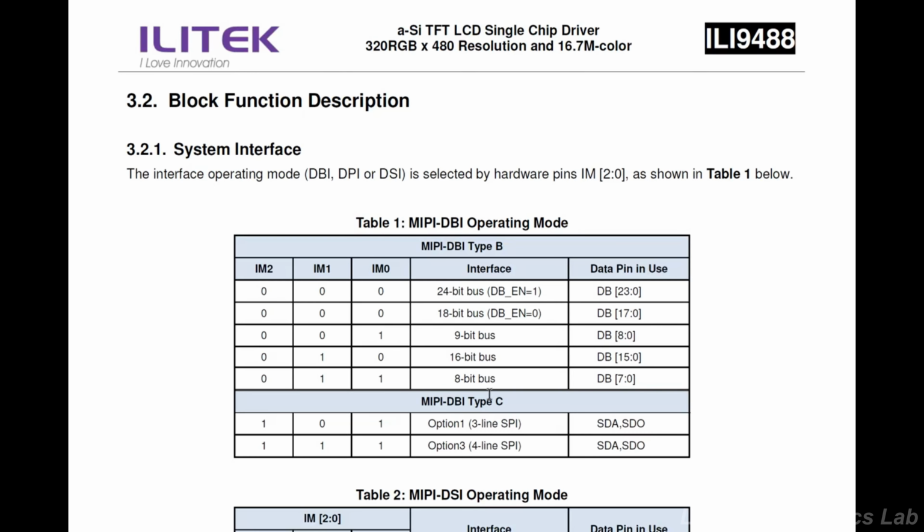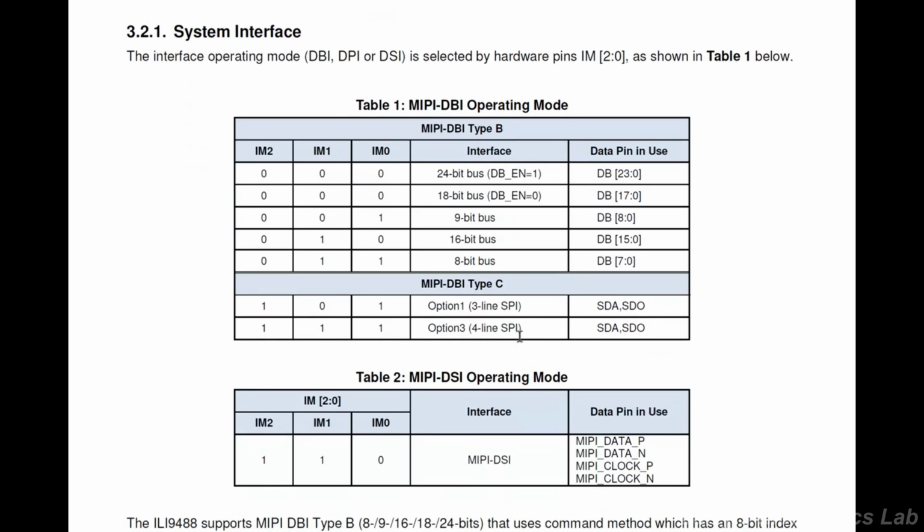So this is the operation mode of the microcontroller inside, see? And it can do 24-bit, but we don't have it physically on the interface. We do not have this many bits. We only go to 18 bits. But the microcontroller inside the display, this ILI 9488 device, can do 24-bit, right?